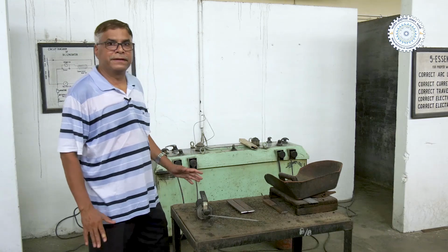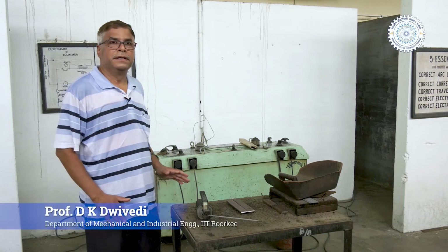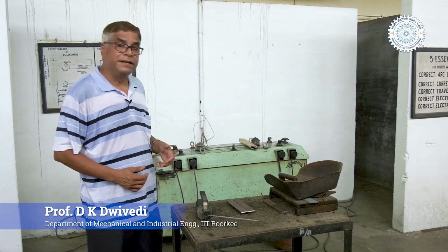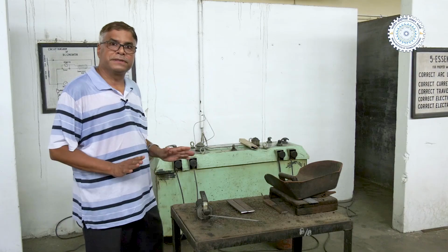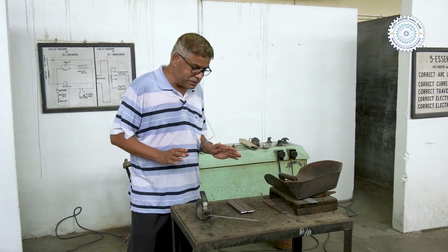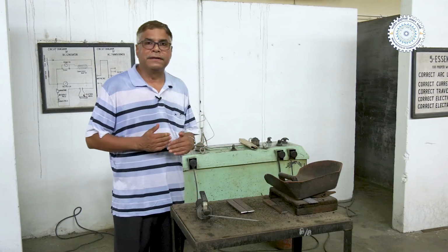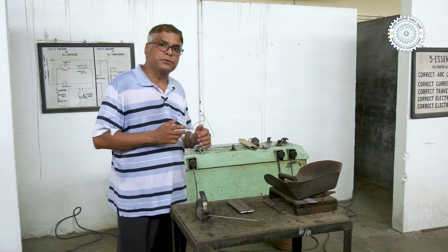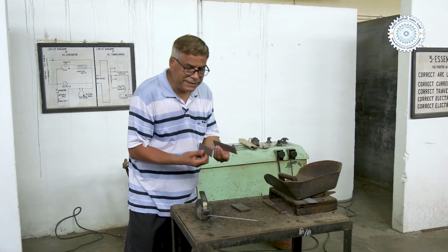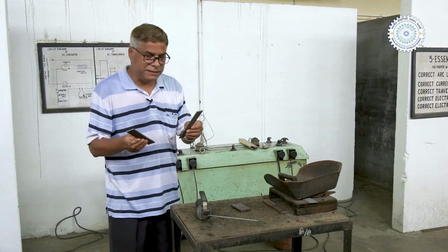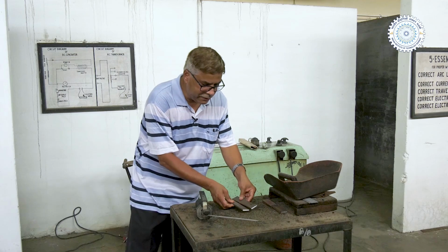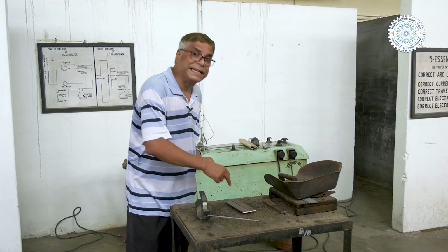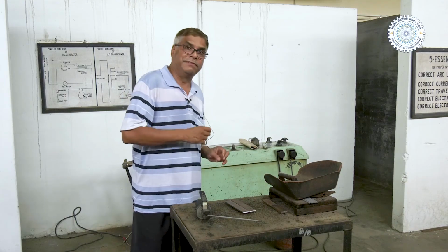Hello students, in this practical demonstration we will be talking about the shielded metal arc welding process, and later on we will see the demonstration of this process. You know, this process is based on the very simple principle of using the heat being generated by the electric arc, and that arc heat is used for melting the edges of the plates. Like these are the two steel plates, so these are to be fused in order to have the metallic continuity along the weld line.